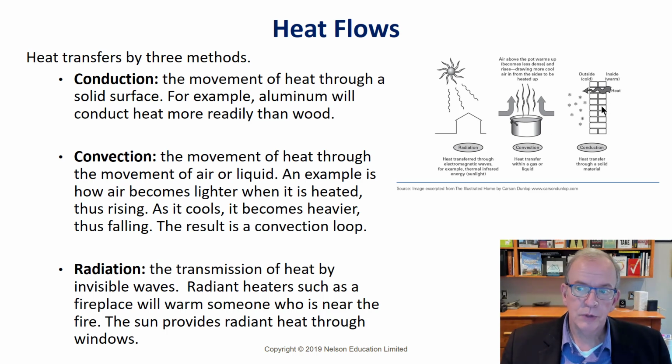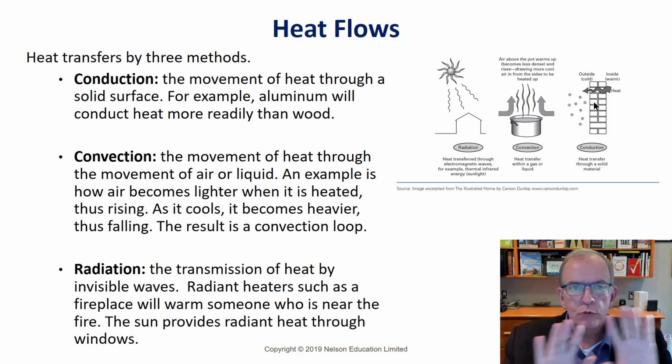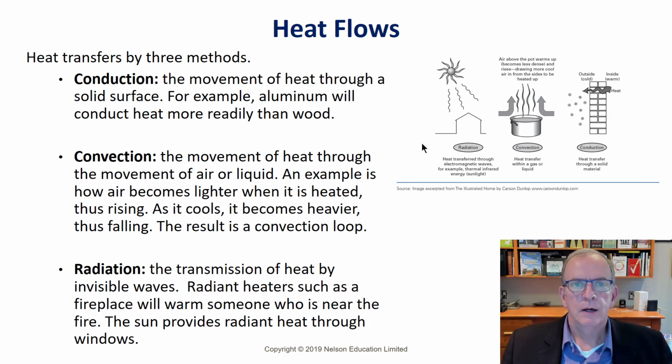This is showing a solid brick wall. Through a solid brick wall, heat travels very readily. So you lose a lot of heat in an uninsulated solid masonry house, like half of Toronto is, the older houses. I don't know, there's probably about 700,000 or 800,000 houses like that in Toronto. So there's a lot of heat loss through those structures. New structures, like the Brook drawings that we've been looking at from the chapters in the textbook, Understanding Construction Drawings, we see that they do put a lot of insulation, and we do tightly seal those houses.